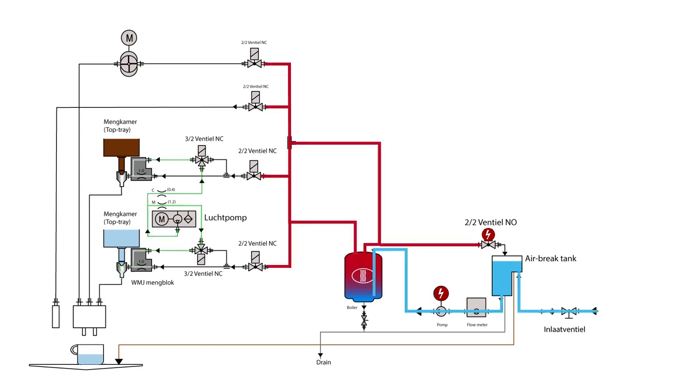The sequence is now repeated for coffee. The dosing coil for coffee is actuated and coffee is being dosed. Shortly thereafter, the two-way valve opens. Water flows to the water restriction receptor, and air that is drawn in through the air channel is added. The water jet is mixed with coffee in the mixing chamber. The three-way valve at the coffee side is opened to produce flat coffee without a crema. In this instance, the relation between coffee with crema versus flat straight coffee is 75 versus 25%.